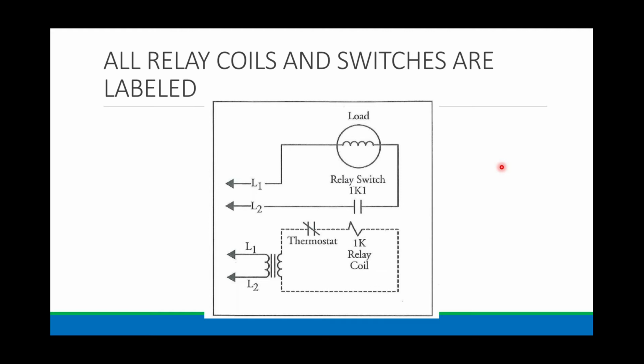So what are we looking at here? Well, you see the L1, L2, darkly drawn lines with the arrowheads. That's your 120 volts. And the way it's drawn is anything that's on the line voltage side is drawn above, and anything on the low voltage side is drawn below. Low voltage wiring is either dotted lines or lightly colored lines. But the L1, L2 that you see on both drawings is the same power. So what's the difference? There's my transformer.